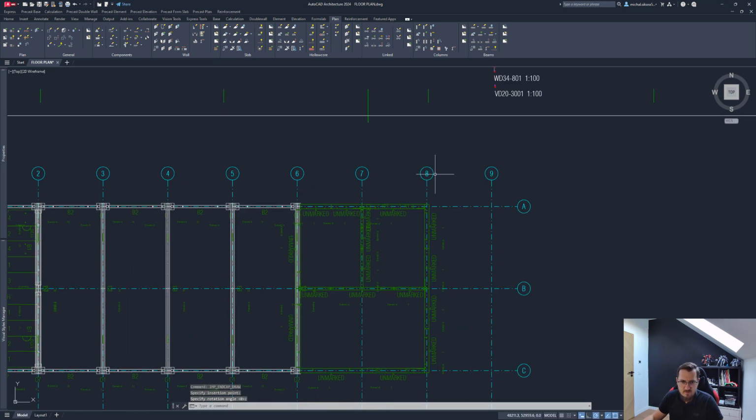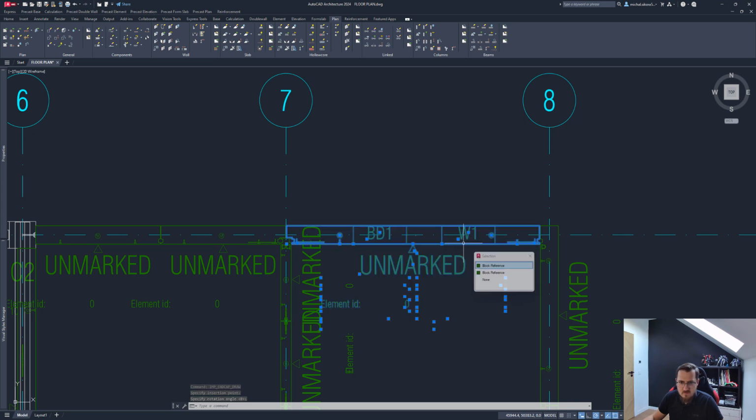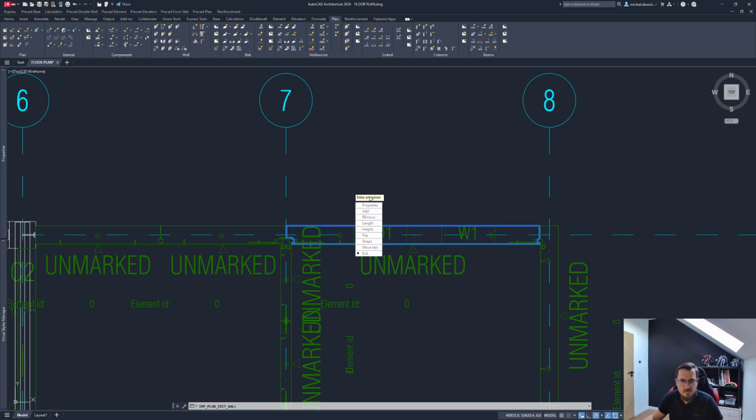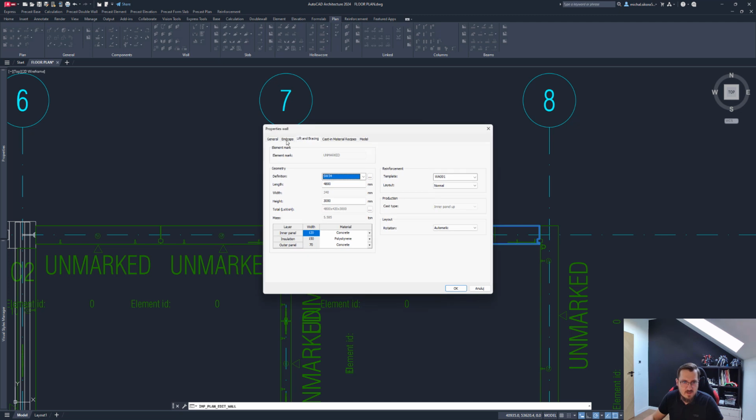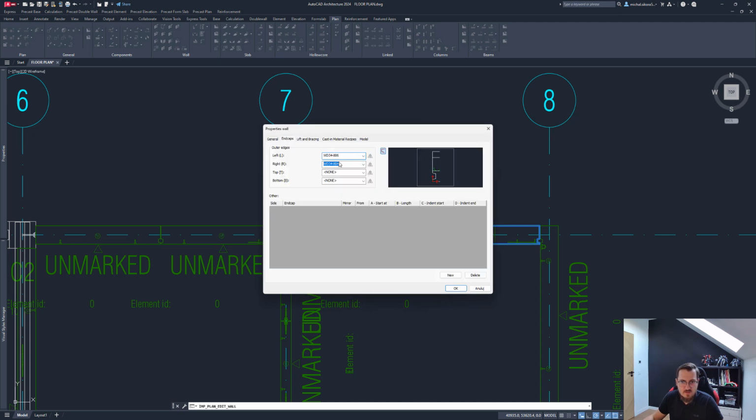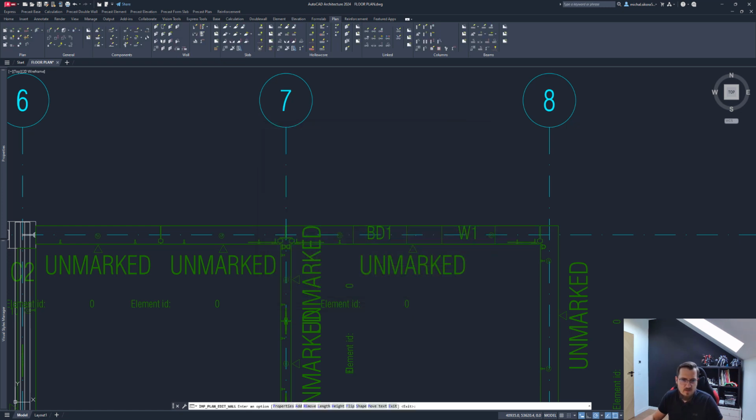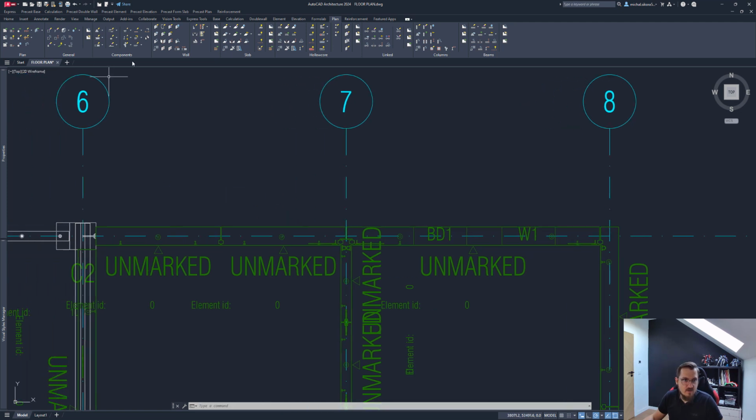Yep. Let me verify one thing. I'm going to edit the wall, go to properties and select the end caps and see what kind of end cap was applied. That's 804. Okay, so that's perfect. We can still do that. So this is this particular end cap. So I'll create this end cap as well for us, and for it, of course, I can place the reinforcement. While I'm here, a quick connection.